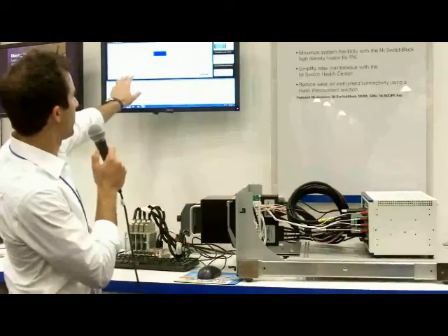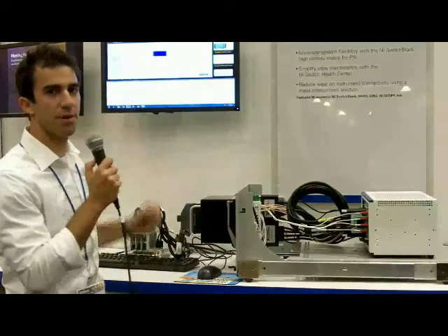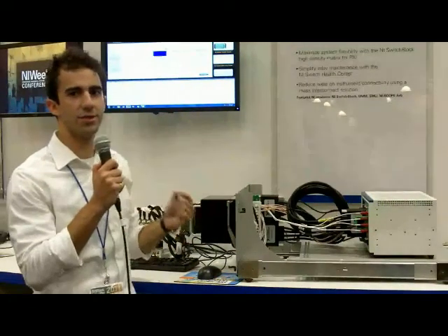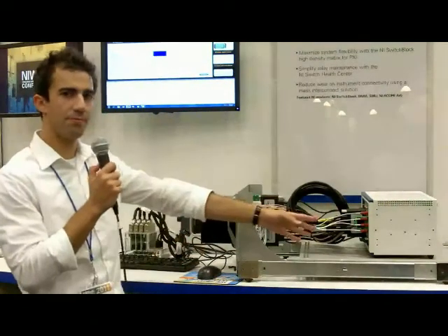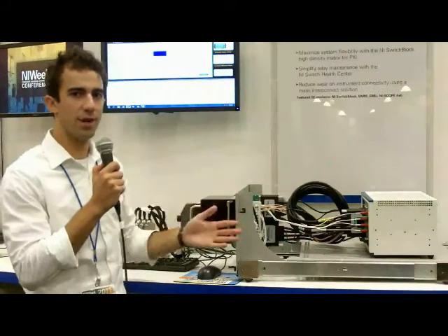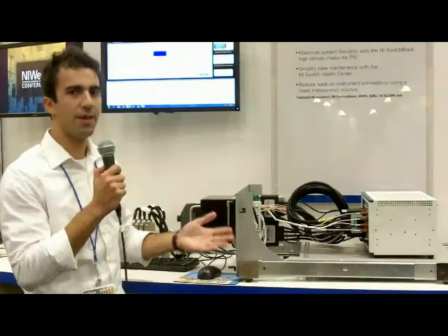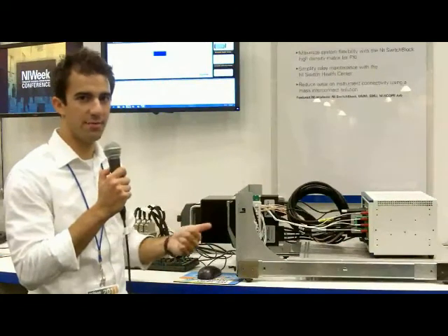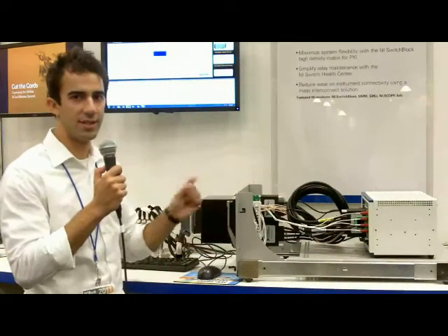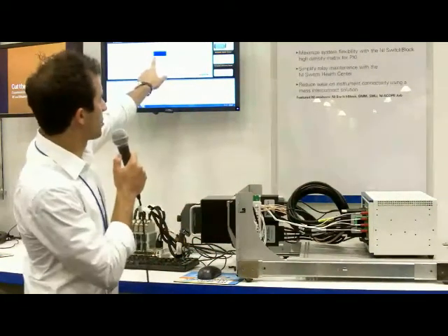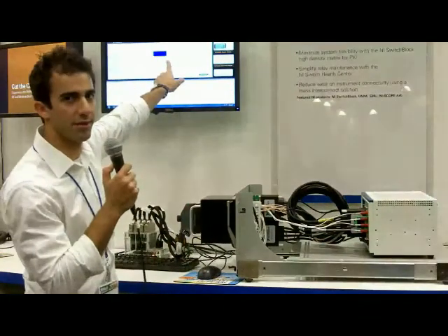And the two tests we're running are a linearity test to compare the results of our data acquisition system to our DMM. And so we're going to source a voltage ramp using the source and measurement unit, and we're going to measure that back using both the DMM and the ADC and see the difference. And so we've actually plotted the difference in this graph up here.